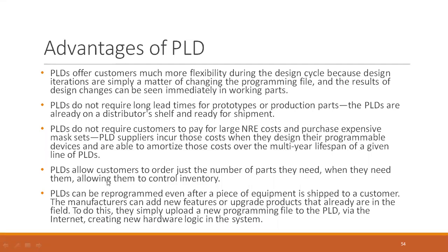This is one more best feature of the PLDs. Even though PLDs are working on a customer site, if they want to reprogram them, add new features, or upgrade the products, they can do it while sitting at a geographically large distance, by uploading the new programming file to the PLD via the internet, creating new hardware logic in the system.